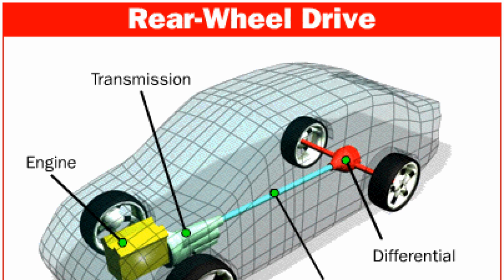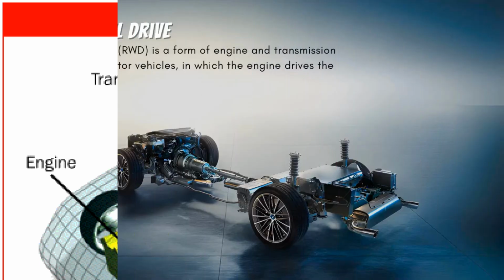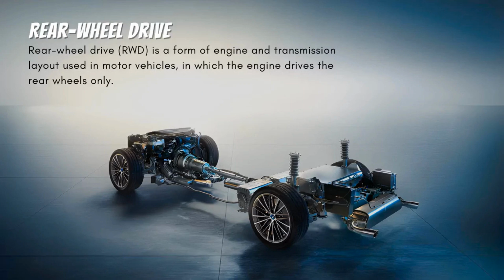Four-wheel drive. All-wheel drive requires all the elements used in the design of front and rear drives, as well as a transfer case. It is the transfer case that distributes torque between the front and rear axles. The all-wheel drive vehicle will have 2 inter-wheel differentials. There are different types of systems with individual features and disadvantages. For example, full-time all-wheel drive involves an inter-axle differential, the locking of which allows you to distribute torque between the axles depending on the situation.